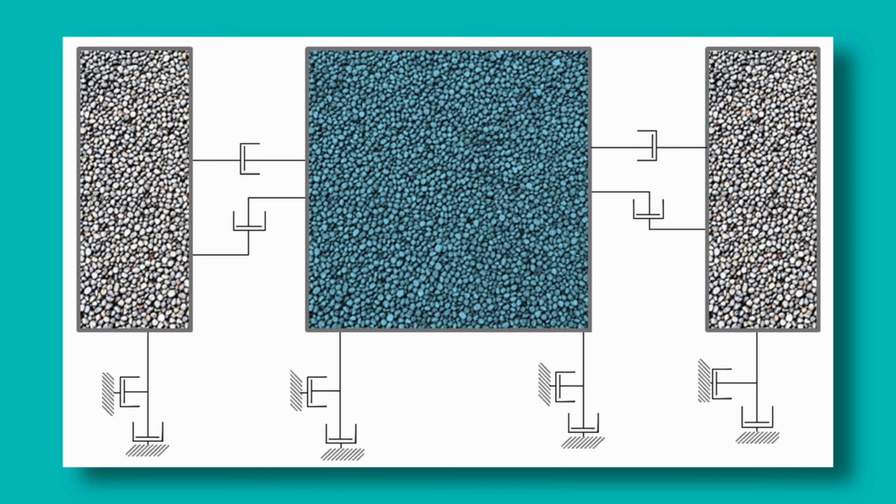One of the available features in ELS to address this challenge is the use of absorbing boundaries based on Lysmer damping. These transmitting boundaries are applied along the sides of the cylindrical model and at the base. Their purpose is to absorb outgoing wave energy, effectively simulating an infinite domain rather than a finite one. With these absorbing boundaries in place, waves no longer reflect back into the model. Instead, they dissipate naturally at the boundaries. This allows us to apply the full load history without worrying about artificial reflections.